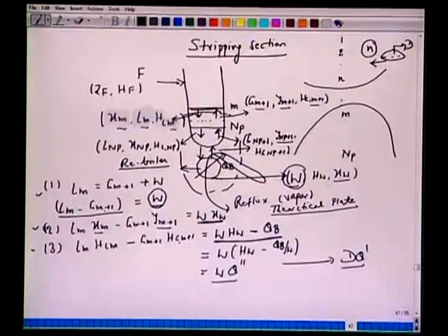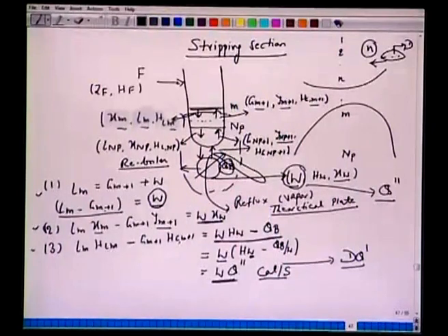So again, this is a hypothetical stream that leaves this envelope with molar flow rate W, but it contains an energy of Q double prime to incorporate the heat energy of the reboiler which you are giving, QB. So the unit is calorie per second: calorie per mole times enthalpy, and for W you have calorie per mole to make it calorie per second. So this is the rate of a hypothetical stream with molar flow rate W which leaves with this much energy.